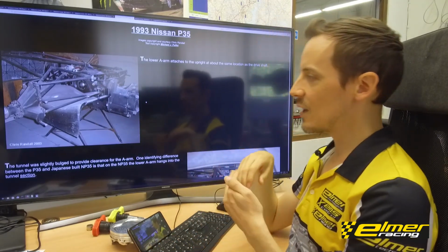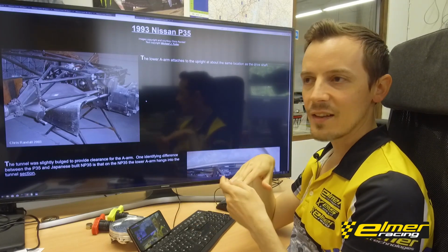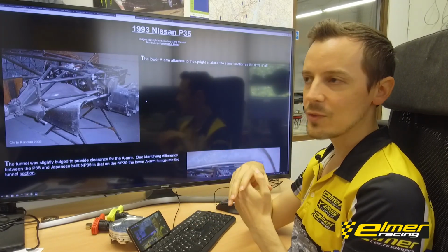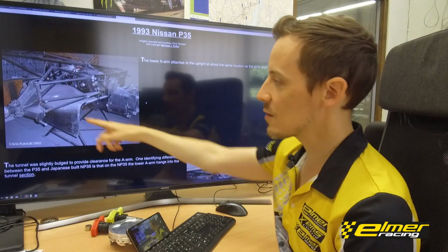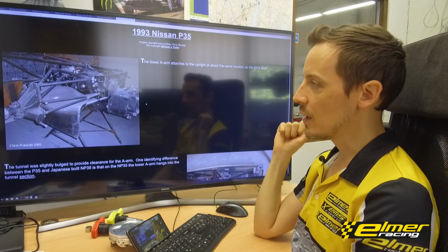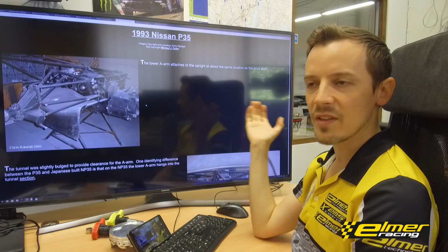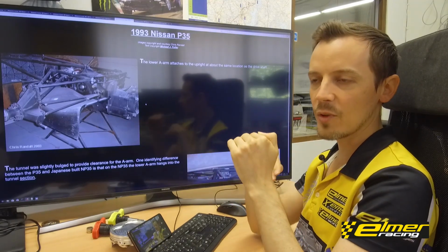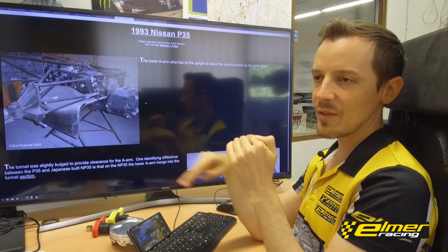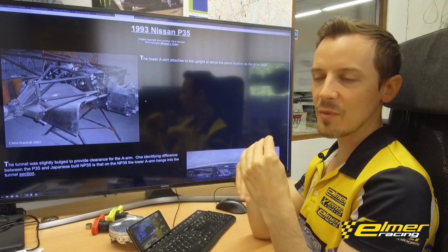But if you can't run the air through or run that as aggressively, then you're not going to have gains by running a larger diffuser. So that's one of the important things, and this is what they've been doing on some more modern F1 cars. I believe Red Bull maybe started doing that some 5, 7, 10 years ago, bringing the suspension components in the rear up as far as possible to improve the airflow over the rear of the diffuser bodywork to again increase the suction from underneath the car.